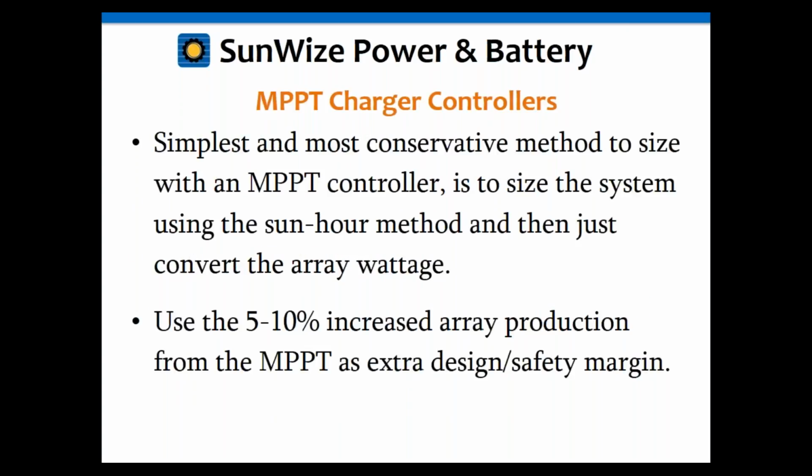MPPT charge controllers. I think we had a pretty good webinar on that last time about MPPT versus PWM. The simplest and most conservative way to size your system is to size it, as I mentioned before, and assume you're going to use a pulse width modulated controller. And if you want to use an MPPT, just use an MPPT.